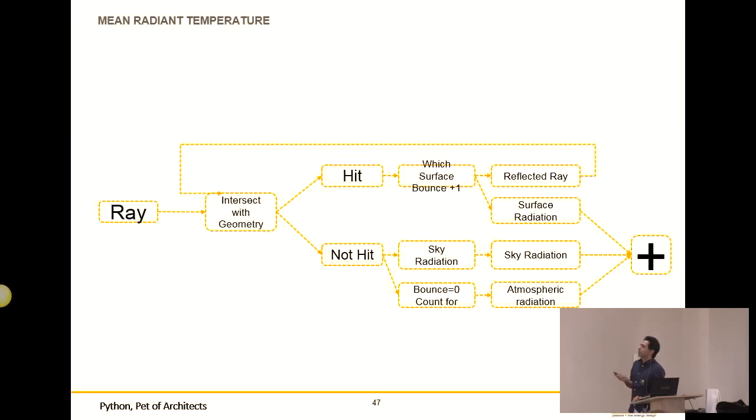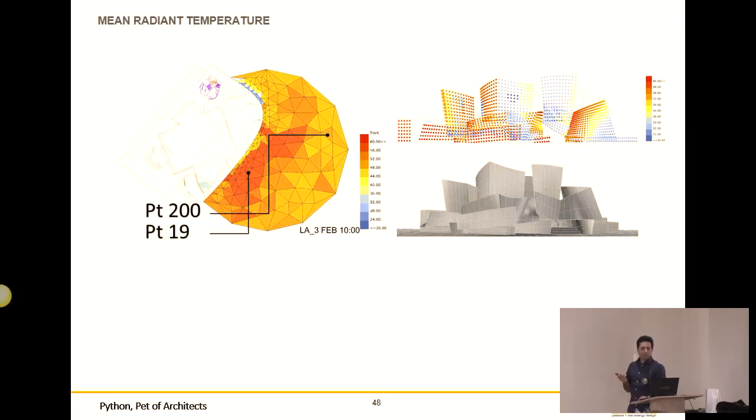So we made this very fast, quick process with several Python scripts, overlaying all of the information at the end to see how comfortable each point is. We also optimized the mesh, which points we need to examine. For the points closer to the geometry, we are more interested in the result than for the points further away. So we can analyze the outdoor comfort at different points and visualize it even for very complicated geometry.